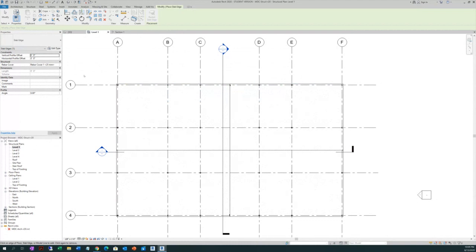Last night, what we did on the walls was a reveal or a sweep. We did a reveal. So that is a 2D, a profile, a wall sweep. Now the mullions, when we did the mullions, it's a profile. Mullions, correct? You go to the family, it's a 2D. That's it. Here, the same situation with the slab edge. This is a profile.